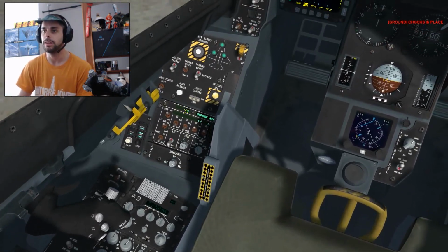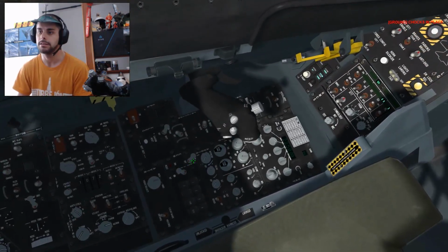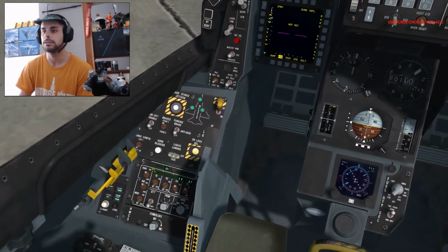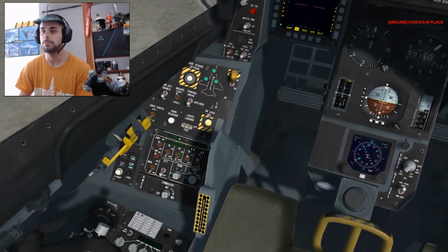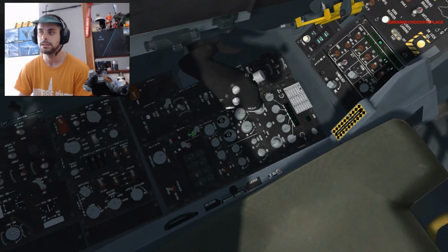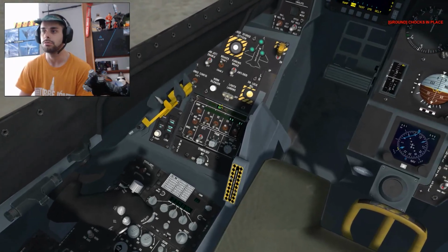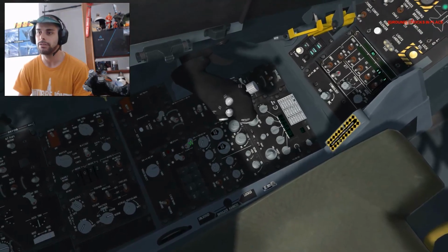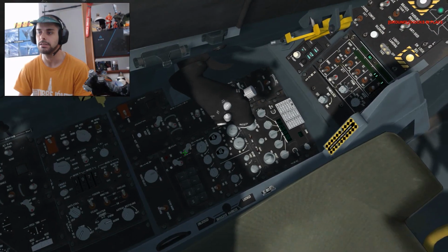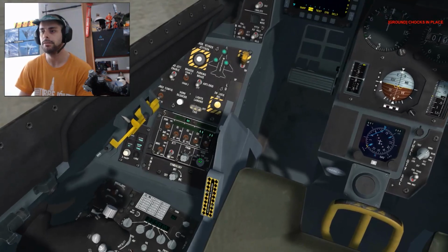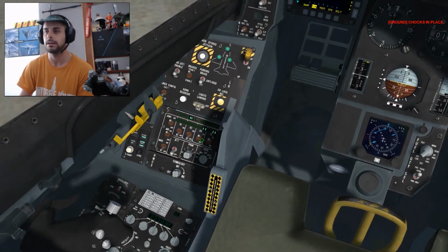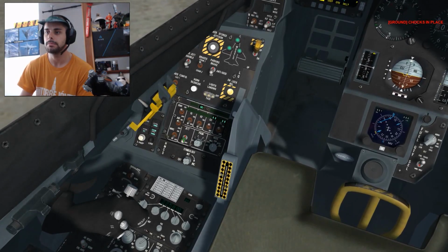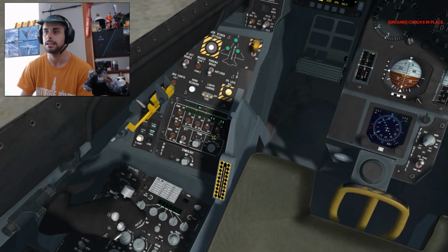If you have a go here, it is good, but if you get a no-go in here, now it's already a go, but almost always when you forget this switch, you are going to get here a no-go or a degraded, okay? That means that you are forgetting this switch over here, okay? Perfect, this system is already on. Never ever push this jettison button, because you are going to drop all your flares, and that's not good.